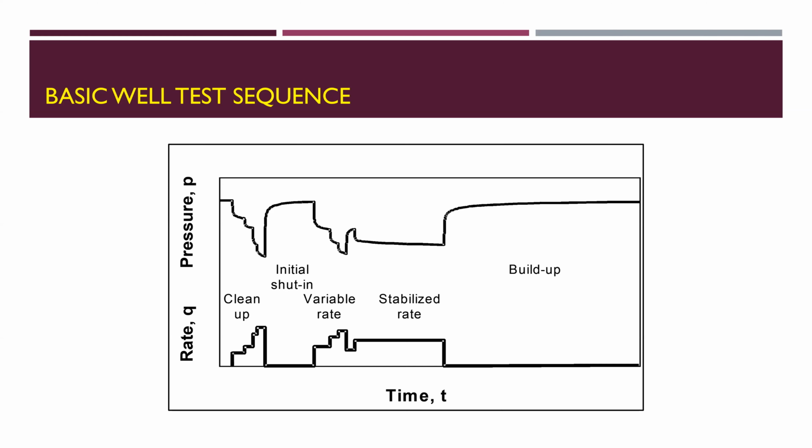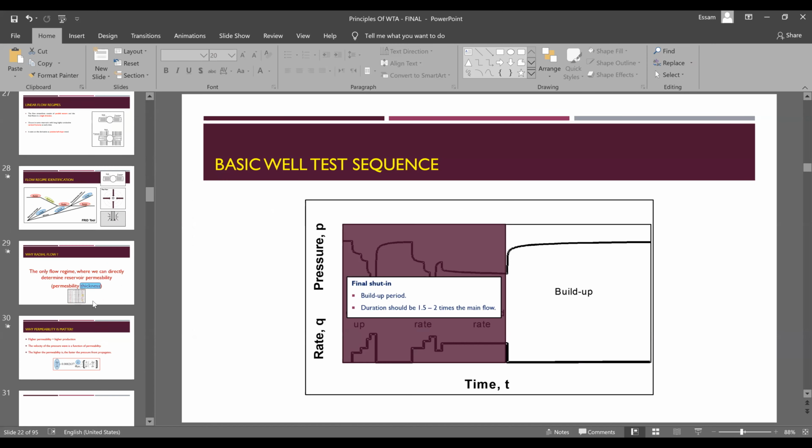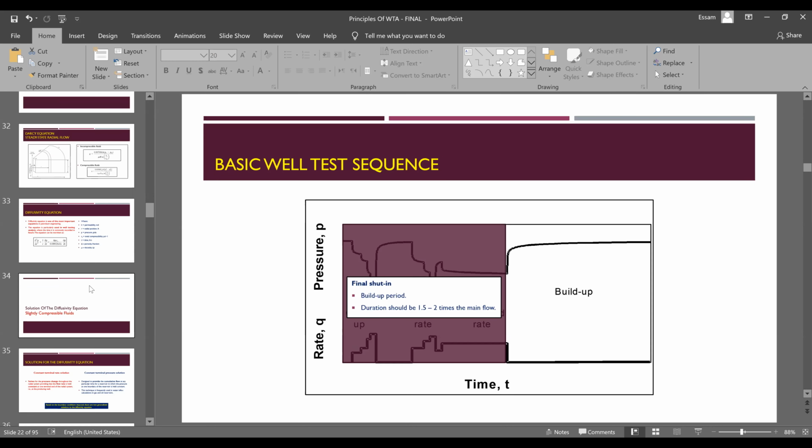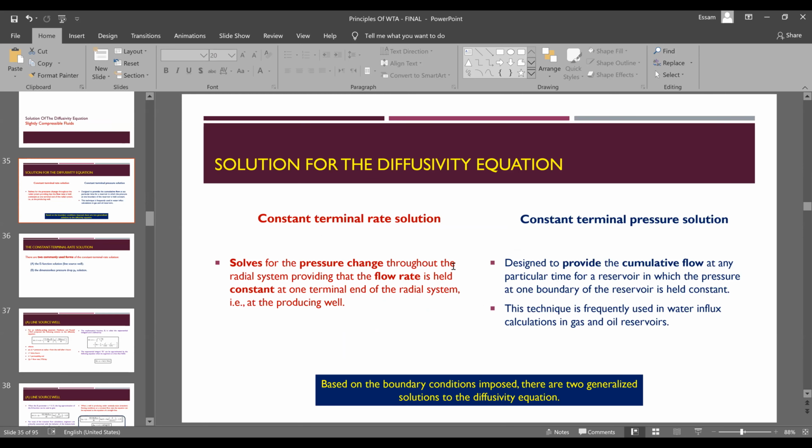Understand. All right. Can you please also elaborate on when you're talking about constant terminal rate solution and the constant terminal pressure solution? So, yes. The constant terminal pressure solution has not been discussed in terms of well test analysis because it is not accounting for pressure change.